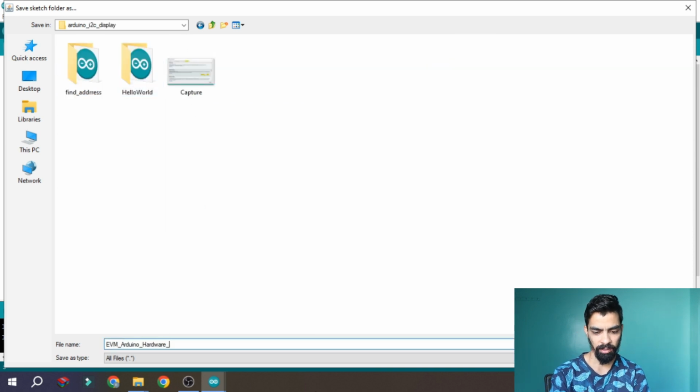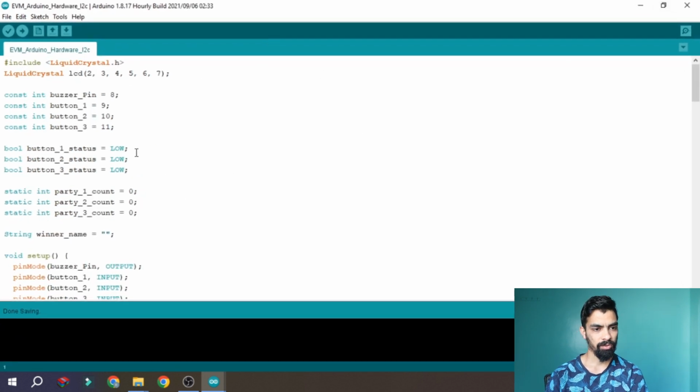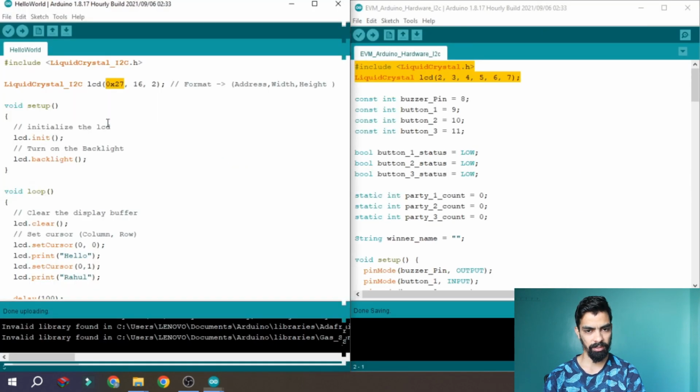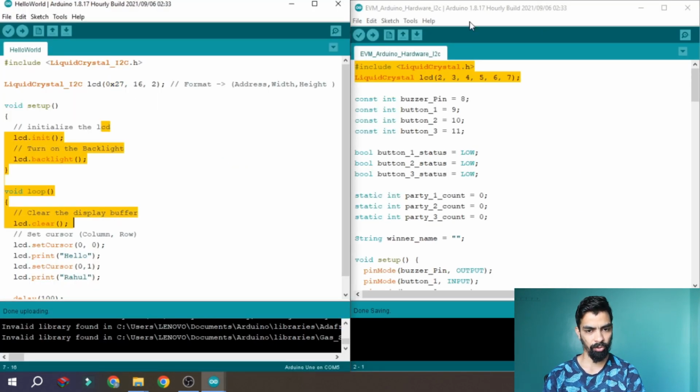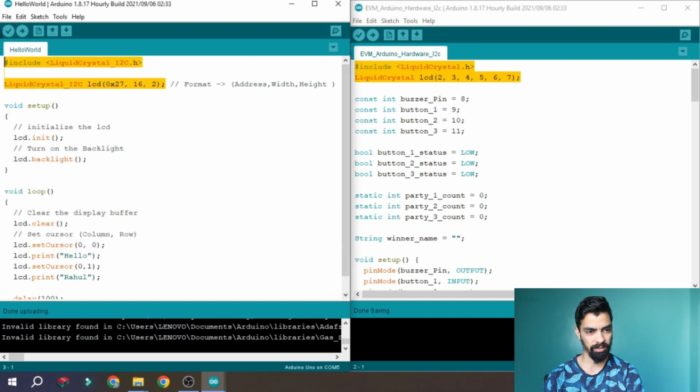So this is the reference code for you. So if you want to replace, you can check this reference code also and compare with your existing project. Okay, so first we have to remove these two lines because that is for the GPIO. So this is my GPIO code, and this is my I2C code. So these two lines we don't require, so just replace this.